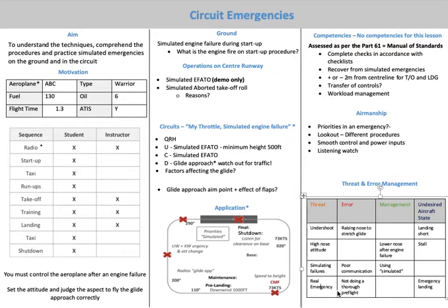Takeoff and landing: we'll have a look at the aborted takeoff practice on the runway first, but the engine failure after takeoff will be done only by me. Then in the circuit area, I'll demonstrate engine failure upwind, crosswind, downwind, and then I'll hand over and give you a go as well. Then taxiing and shutdown will be done by you.